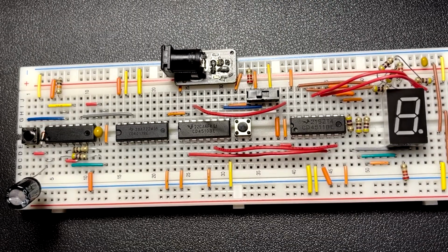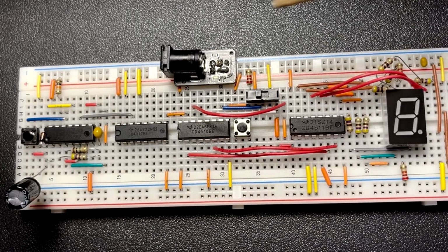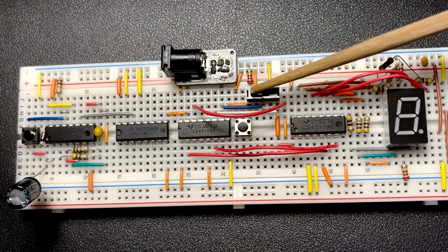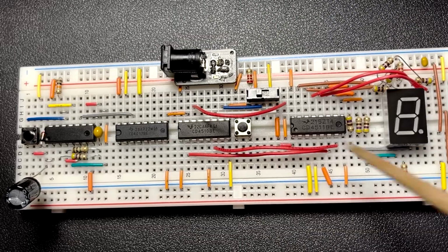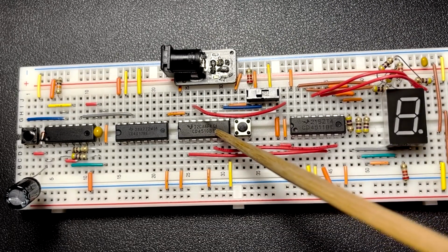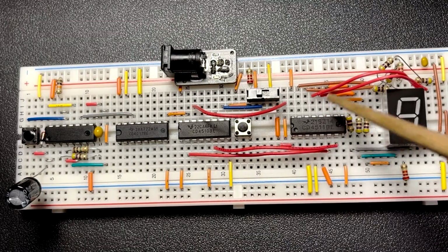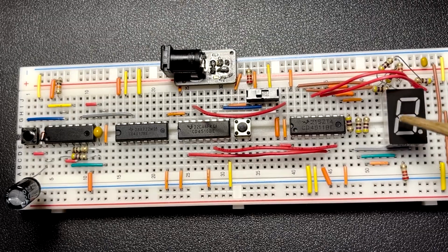So this is my final counting circuit. All of these parts are from previous steps. And I've also added in a reset button and an up or down count switch. So what this part does is that it converts the signals from before, from binary into decimal, and then all of these output pins will output to the 7-segment display.